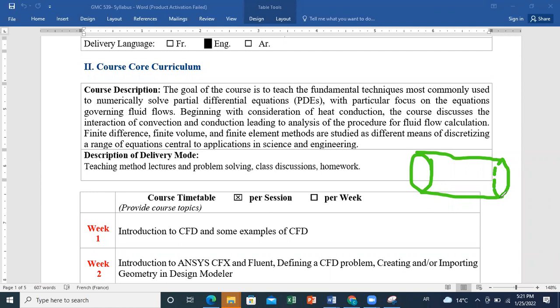And this can be much more complicated when you include the effect of turbulence, because when you have high Reynolds numbers, you go from laminar to turbulent regions. So you have what is called formation of eddies in your flow. You have a lot of turbulence in your flow, and this is very challenging to model. This required a lot of research on this topic. And until now, we are still trying to find if it's possible to get an analytical solution, and we still do not find solutions for this.